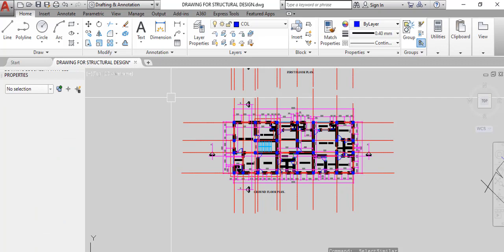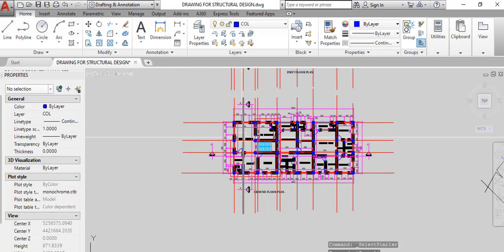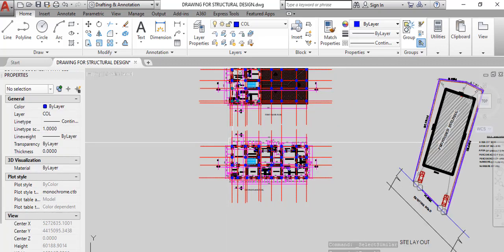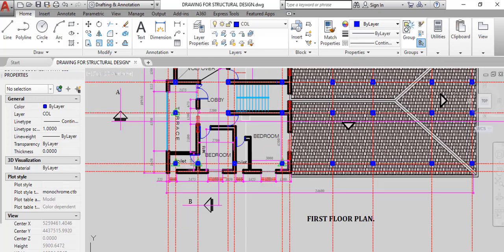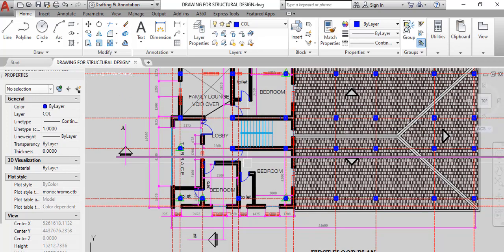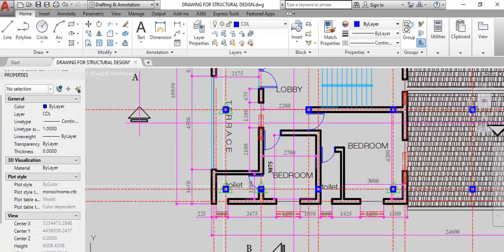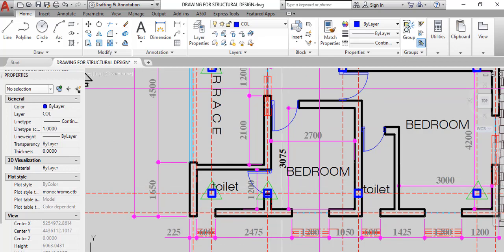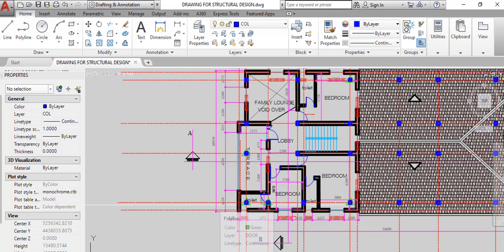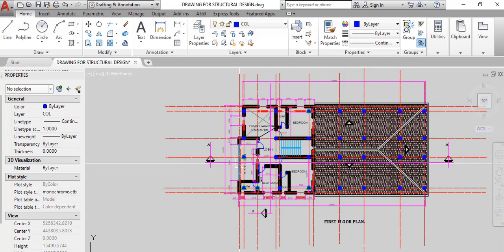This is very important. So with that, we carry this and superimpose it on this other first floor, which shows that this from here cantilevered out. So it cantilevered, and some of the columns terminate at the first floor. It didn't go further than that.